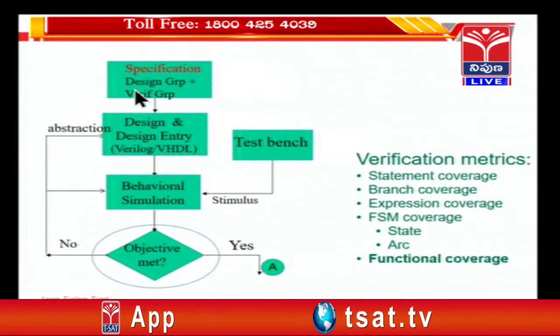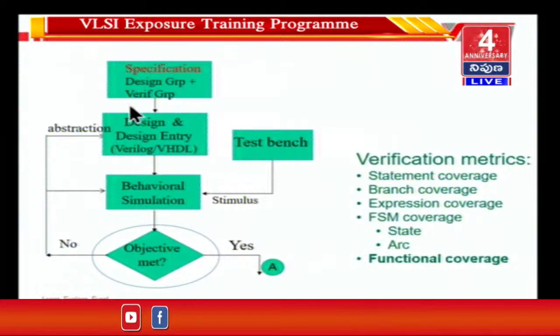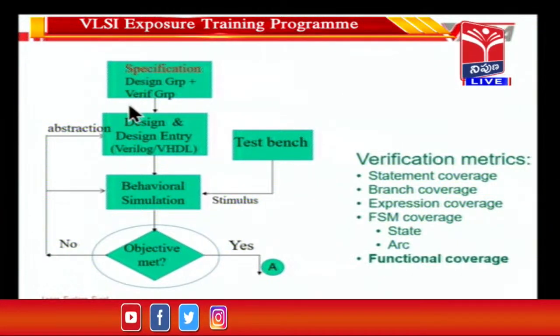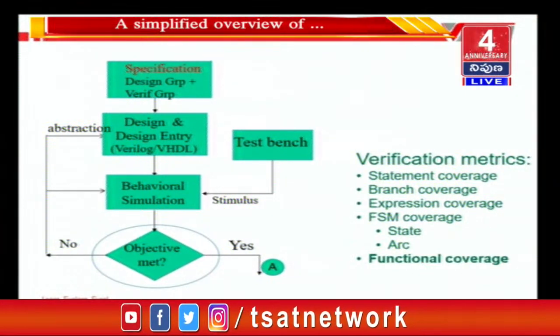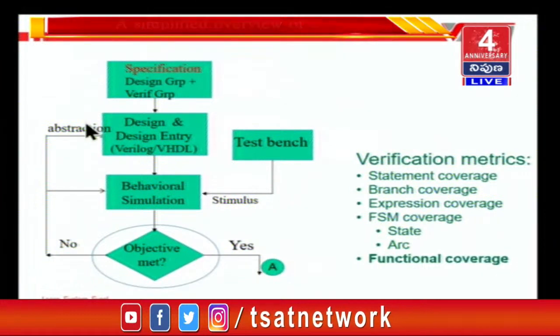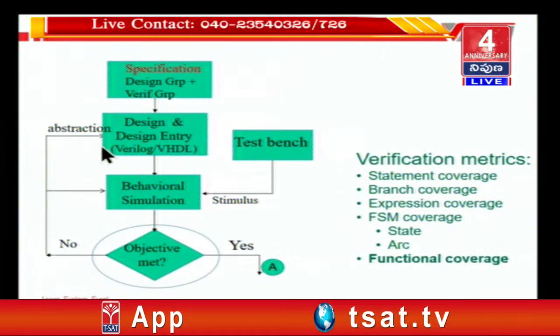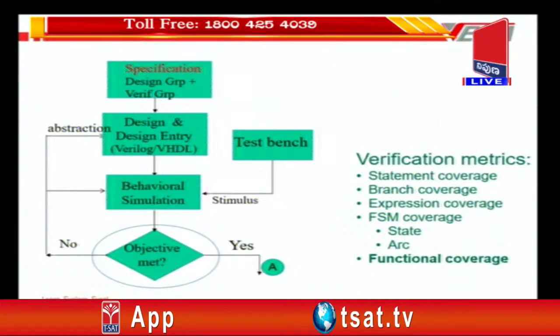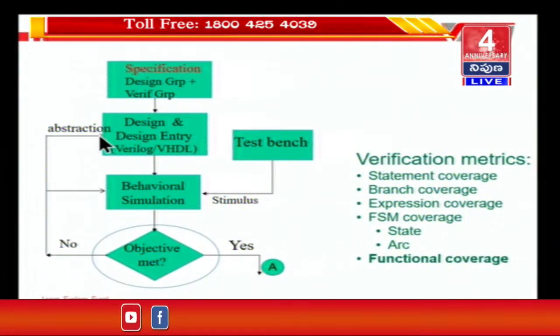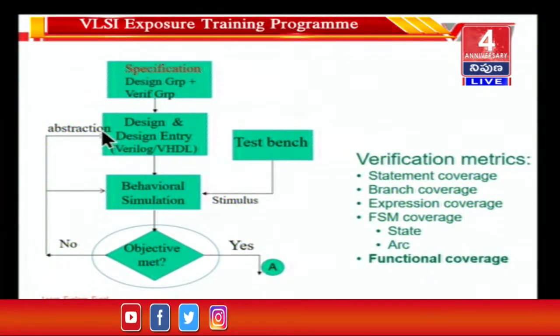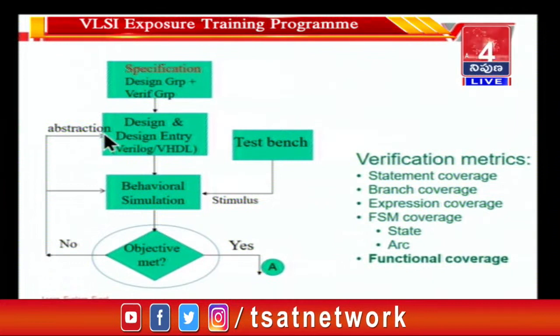They develop what is known as a bus functional model of the particular design, not going into the internals, not knowing about the flip-flops. Just that if a particular input is given to the design on a particular line, then the output is expected after, let's say, 23 nanoseconds or 24 nanoseconds or whatever it is. Accordingly, the verification group will generate an output after 24 nanoseconds.